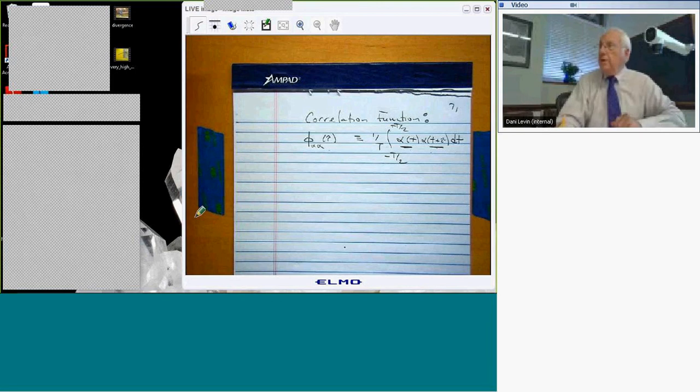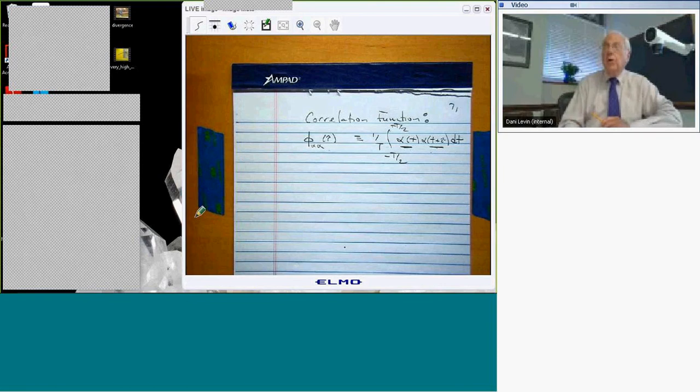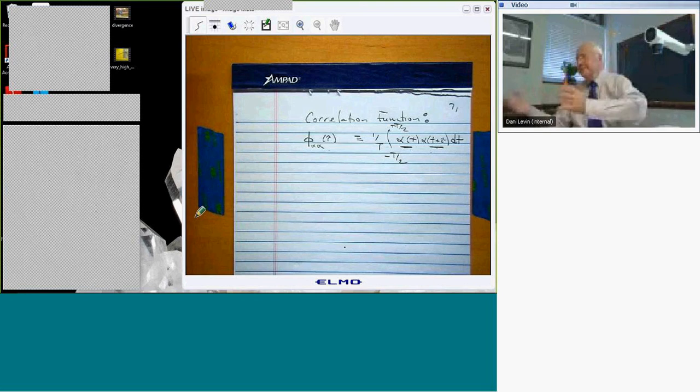And in aeroelasticity, the random input is usually a random alpha naught, which is due to a gust, some atmospheric gusts exciting an aircraft wing or airfoil, and the response is the motion of the wing. One of the difficulties, of course, is that you usually have a dynamical system that's much more complex than that simple plate on the spring. You have to think about loads and all the other things you think about for real aircraft wings. But this is the basic idea.